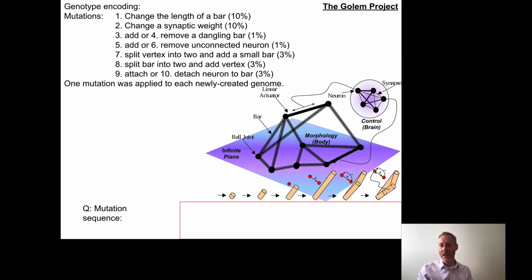So at each time step of the simulation, the value at this motor neuron is supplied to the piston or the linear actuator that's controlling this bar. And if this motor neuron value is positive, that means it's going to apply a force to extend the piston. If the motor neuron value is negative, that's a value that's going to compress or try and decrease the length of the piston. So we've now seen, or in your assignments, you're using hinge joints that have rotational motors.